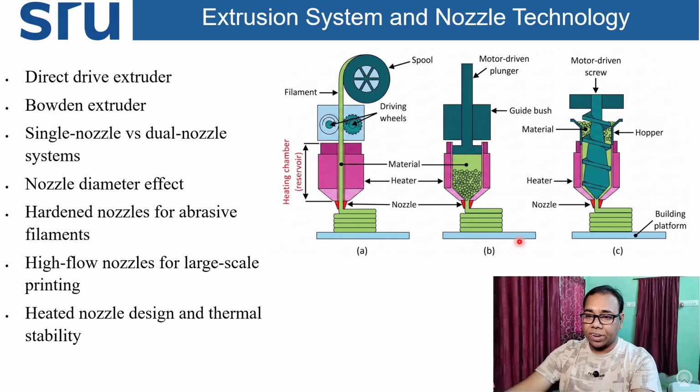So this is a different configuration of the extrusion system. But in this system you can see that your filament material is not there. In that case, powder form of thermoplastic material is used, and that thermoplastic material will be melted here and come out from the nozzle in liquid form. Again it will perform the x coordinate, y coordinate and z coordinate motion to get the different layers information, and then printing will happen in x direction, y direction and z direction.